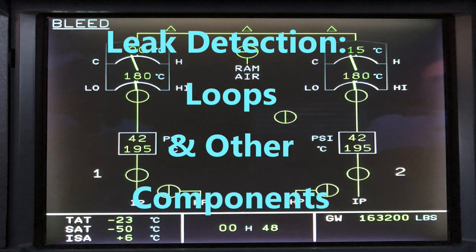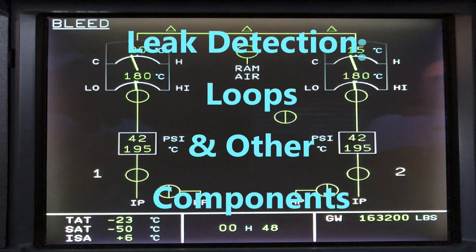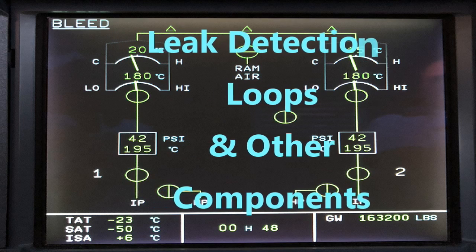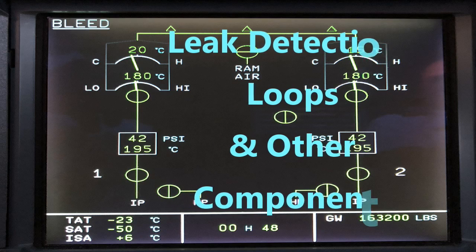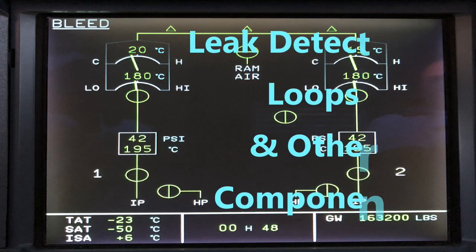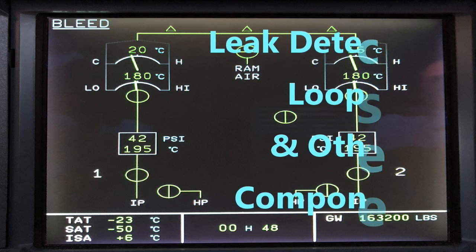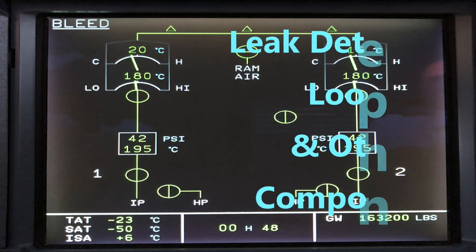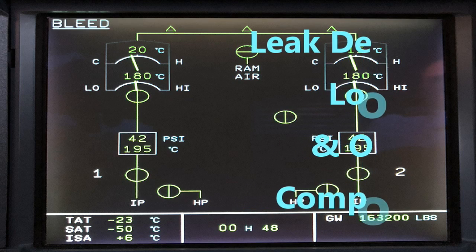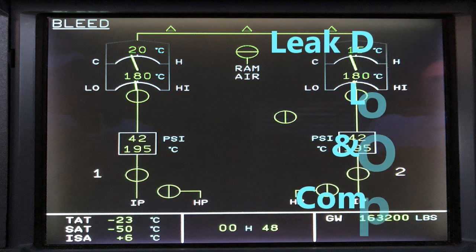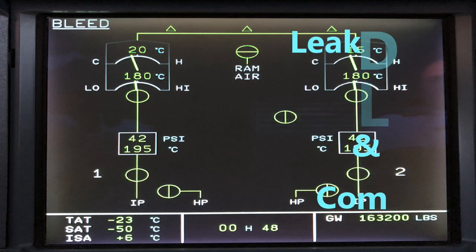And there are clamps and rubber grommets attached to the overheat sensing elements along the whole length. And then you also have them in the fuselage, installed close to the bleed air duct, and they continue up to the check valve on the fuselage.